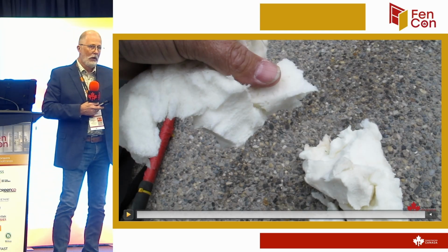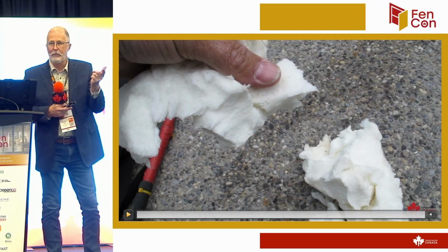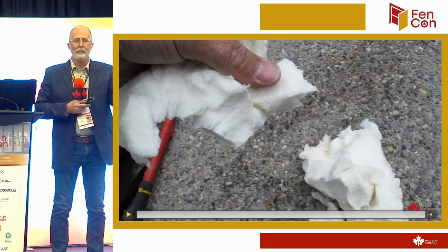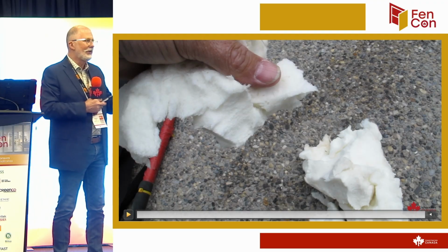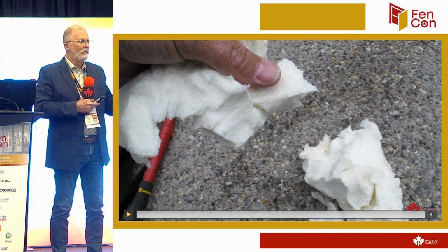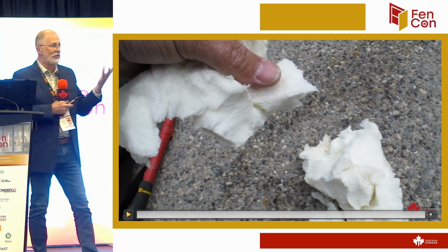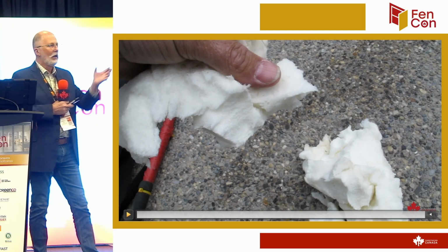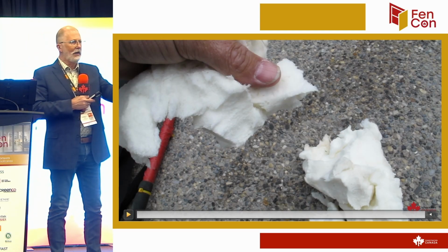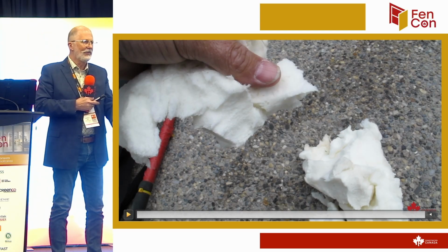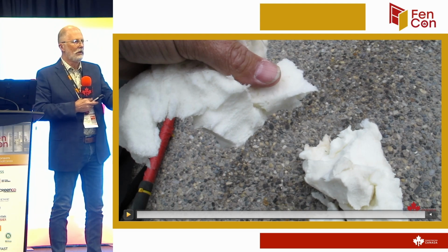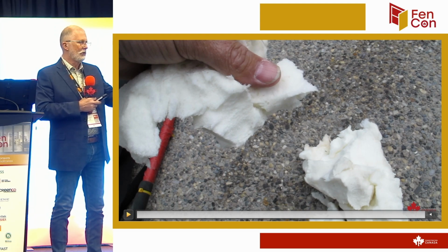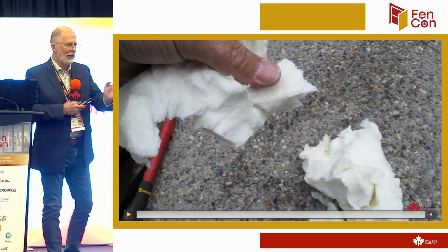Like, let's say you move a window around in the middle of December and it's minus 25 and you break something inside the window and you install it and you don't see it, and just expansion and contraction over the course of the next year, it opens up and water starts leaking out. So you want that air barrier, that plane, to be inboard of the inside face of the upper part of the window, right? You don't care about the jamb extension. You just want it inboard of that connection.